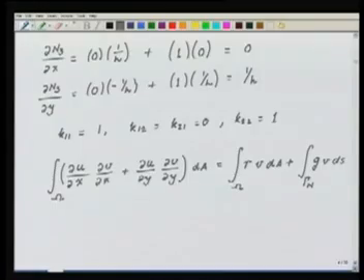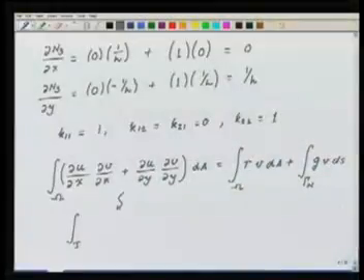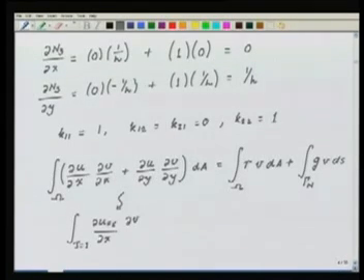So from this, as we have discussed many times, we are interested in the part of this integral on the right hand side and the left hand side coming from our particular element, and that integral is going to give us our stiffness matrix and the force vector terms. So let us take the element. We will say for the element tau equal to 1, for the first element I will have del u del x del v del x plus del u del y del v del y.